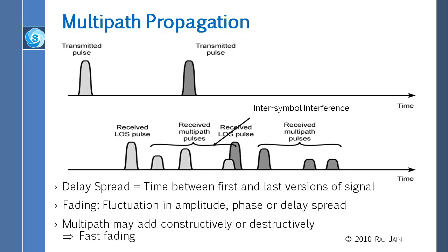You send the first symbol, and by the way, we call these things symbols, not bits, because remember, each symbol could be 6 bits, or each symbol could be 4 bits. We saw that QAM thing. So each dot was what? Each dot was a symbol, right? And each symbol could be any number of bits, right? So if you send this symbol and then you send that symbol, you got 4 copies. So if there is enough multipath, actually it depends upon, first of all, we measure the delay spread.